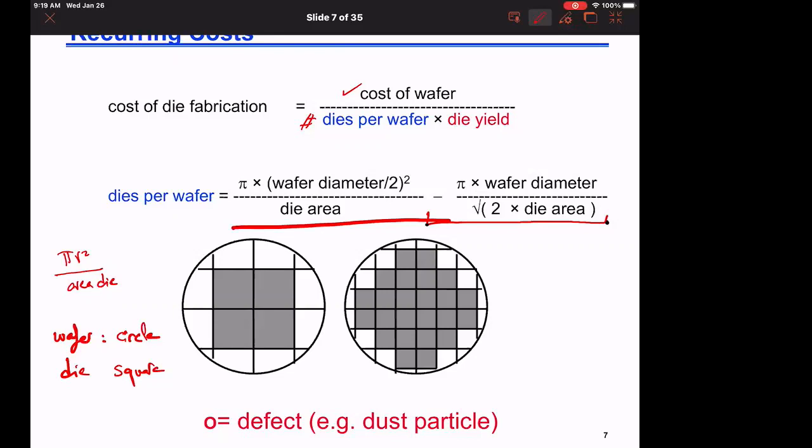Yes, different ICs can be printed on the same wafer. Sometimes what they do is squeeze in between the white spaces. Let us say this is a big chip. I can plug in here some small dies that can still fit in. That's why when a university is collaborating with a company, typically the research folks ask the product engineers, can you squeeze in this new design for me? I want to test it. And typically they rely on what they call the white spaces here to fit in these designs.